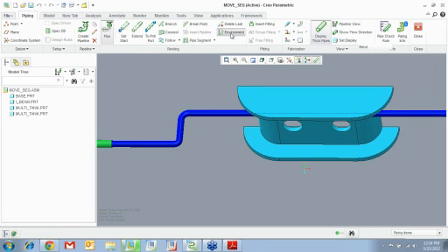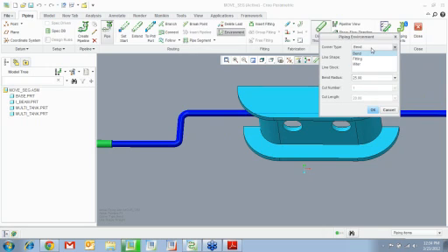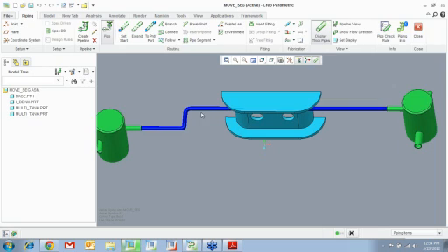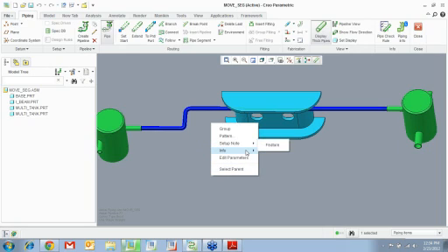You can also go to the environment right here. You can see it's straight or flexible, bend, fitting, or miter. You can choose those examples right here, right? You can select that, and you can do info, set up a node. You can edit its parameters. You can pattern that. You can group it with something else, right? So you can do all these things with a certain pipeline.